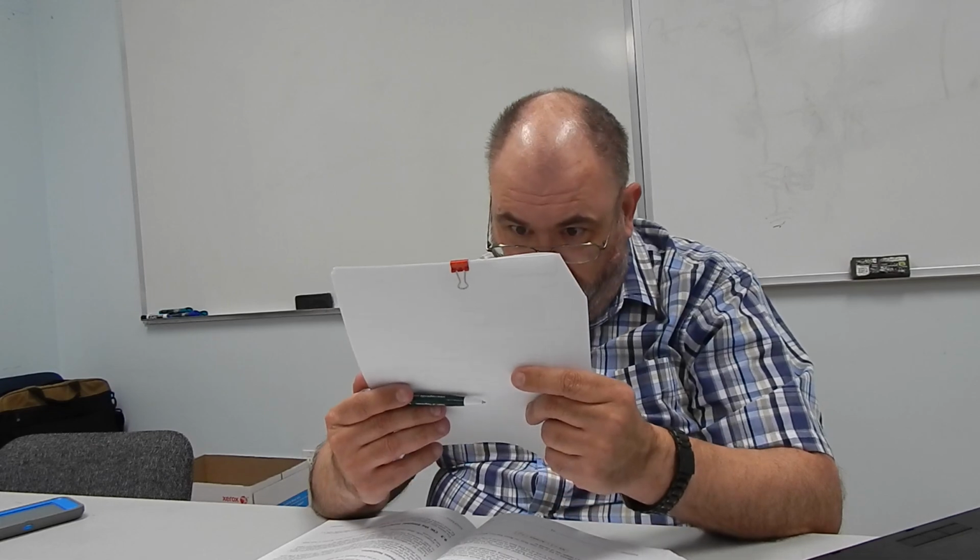Okay. What does the neutralization circuit in the transmitter do? It cancels the effect of positive feedback and eliminates oscillations. We talked at some length about neutralization already. Neutralization in vacuum tube amps cancels oscillation caused by interelectrode capacitance. I think I already said that one. Parasitic oscillations are usually caused by accidental resonant frequencies in the power amplifier. So once again, this is just a bunch of general questions that I grabbed that don't really apply to any one transmitter, but kind of apply to them all.